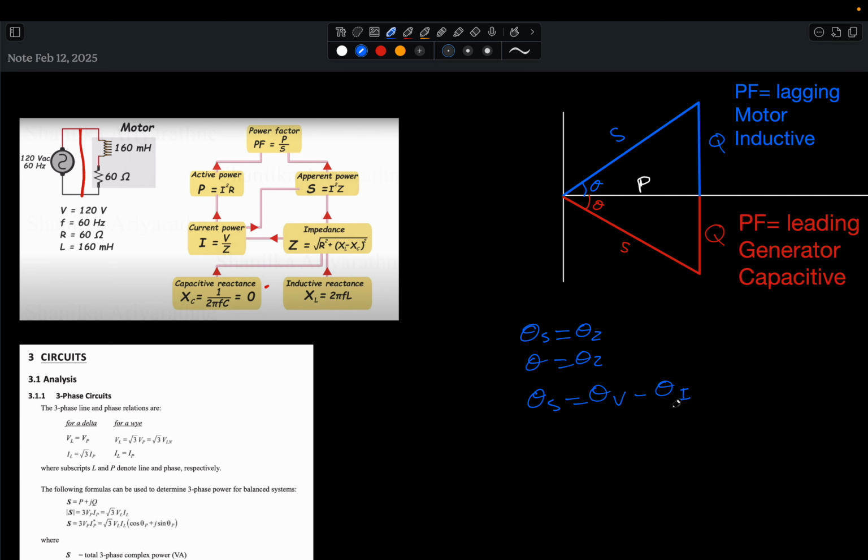So a lot of people get confused when they hear, okay, I'm dealing with a power factor that's lagging. So let's say, for example, I have a power factor at 0.8. What this comes down to, by the way, this decimal is, think of this, power factor, pure unity is 1, which is at 100%, meaning the apparent power equals the active power. There is no form of reactive power whatsoever.